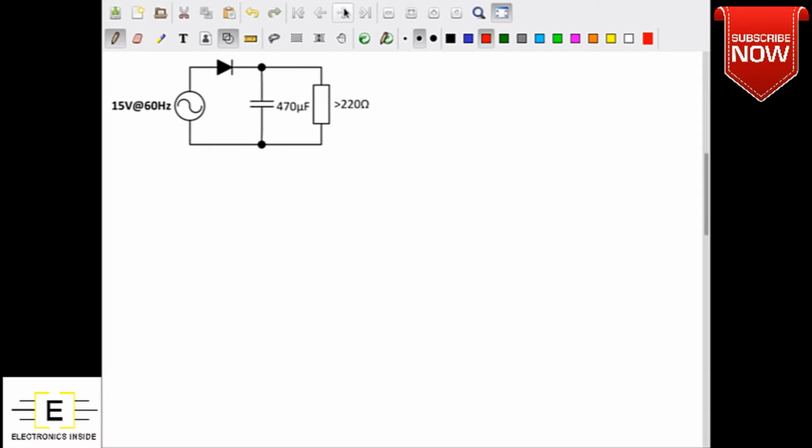So here we have just this little circuit, and we're remembering that we're going to look for what the supply ripple is. So first of all, we know that the absolute maximum value that this is going to charge to is going to be equal to 15 volts, which was V in, minus the forward voltage. So we said the maximum output of this rectifier was equal to V in max minus our forward voltage. So we can compute that.